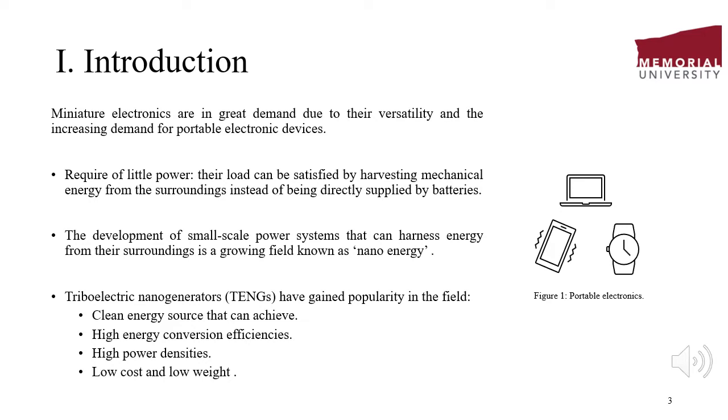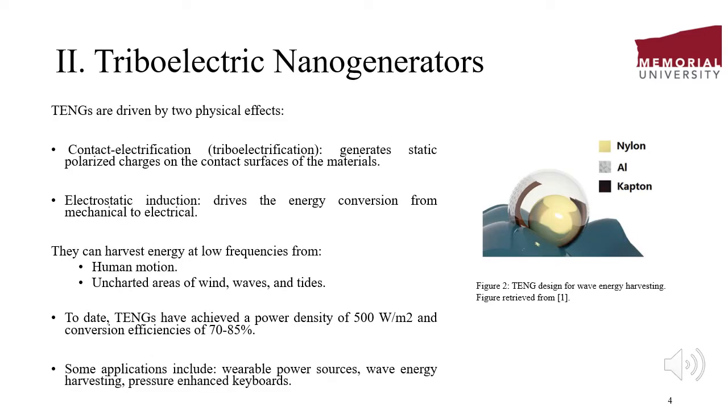Triboelectric nanogenerators have become very popular in this field as they are a clean energy source that provides high energy conversion efficiencies and high power densities at low cost and low weight. All triboelectric nanogenerators are driven by two physical effects. The first one is contact electrification, also referred to as triboelectrification, and is the effect that generates static polarized charges on the contact surfaces of the materials. Then, the electrostatic induction comes into play, driving the energy conversion from mechanical to electrical energy.